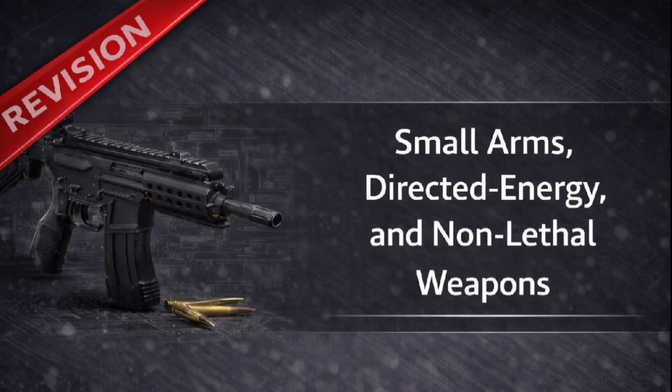The critical insight here is that the massive forward momentum of that moving breech block is used to counteract the backward thrust of the explosion. The energy of the firing event is first spent just arresting the bolt's forward travel. That is a revolutionary concept. You're using the bolt's own movement to achieve safety. It is. This brilliant timing allows for a much lighter overall design than a simple blowback system would ever permit for that same caliber. Truly clever.